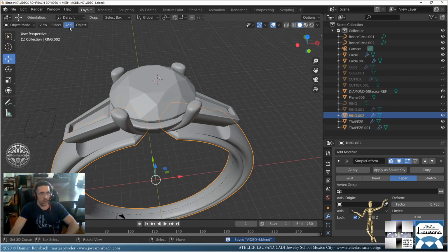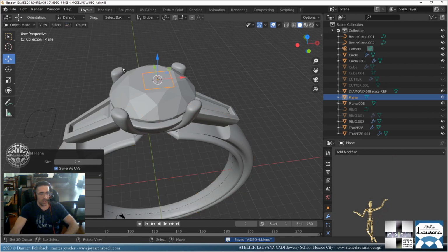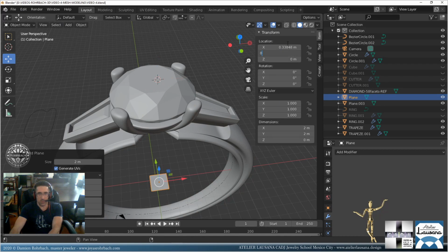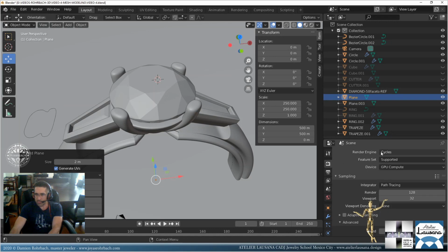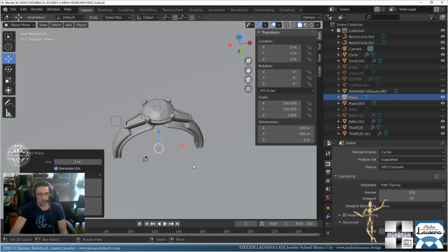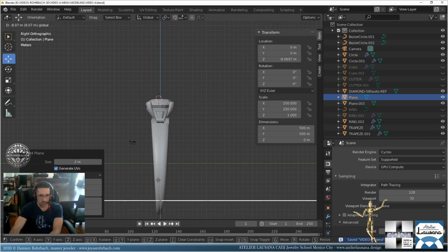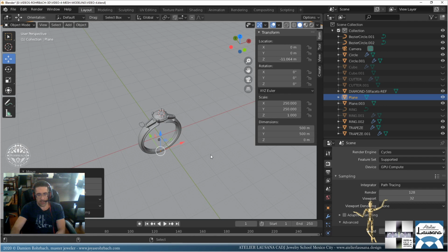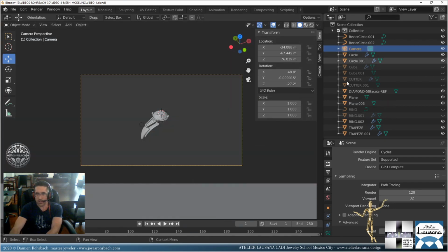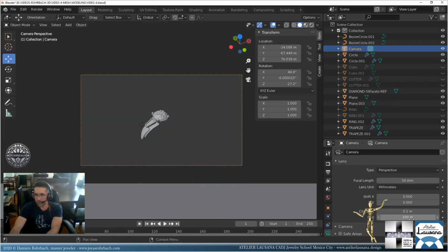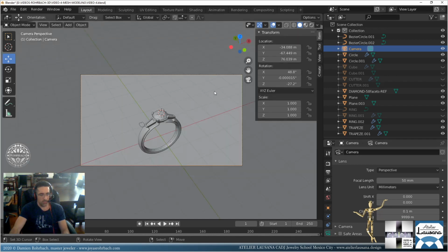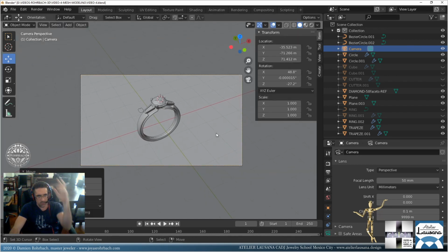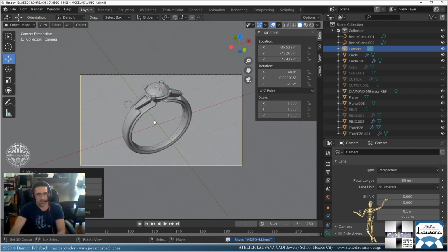All right, quick render, add the mesh plane 0, 0, 0. Let's make it big. Let's put Cycles on. Okay, this is good. Let's put this guy right here. Let's put the view right there. Control 0. Let's configure the camera field. Let's put a huge number right there so we can see far away. Let's change the focal distance, 80.